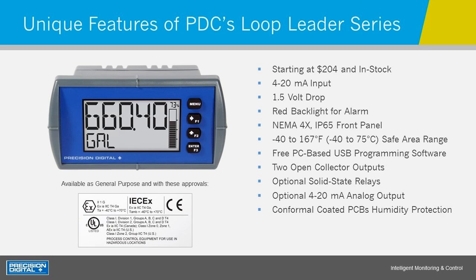You've got those 4 front panel push buttons I was talking about earlier to make programming easier. But we've also got a USB port for software for programming it. We talked about the cost of loop-powered devices. Well, these start at $204, and they're in stock. So when pricing is a concern and availability is a concern, going with a Loop Leader is a great choice for your application. Of course, it's a 4 to 20 milliamp input device, and it drops 1.5 volts on the loop. We talked about the red backlight and the ability to get that watertight NEMA 4X seal on the front.